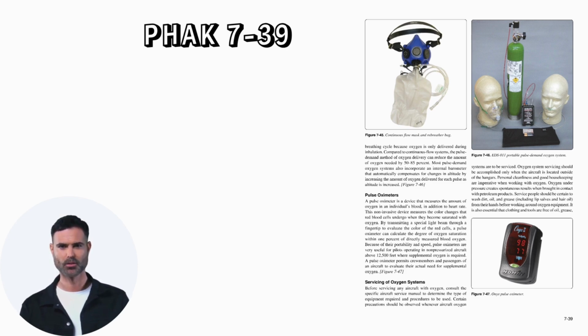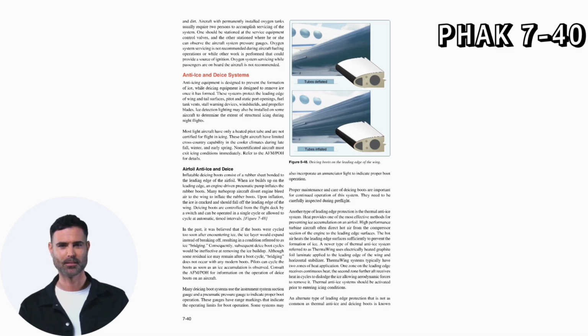Oxygen under pressure creates spontaneous results when brought in contact with petroleum products. Service people should be certain to wash dirt, oil, and grease, including lip salves and hair oil, from their hands before working around oxygen equipment. It is also essential that clothing and tools are free of oil, grease, and dirt.